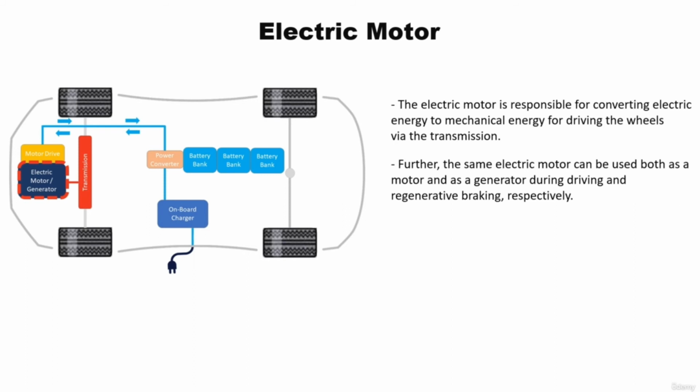Finally, the two key parts of electric cars are the auxiliary battery and the power electronic controller. The auxiliary battery provides electricity to start the car before the traction battery is engaged and also powers the vehicle accessories. The auxiliary battery is usually 12 volt for current vehicles but may be increased to 48 volt for future vehicles.